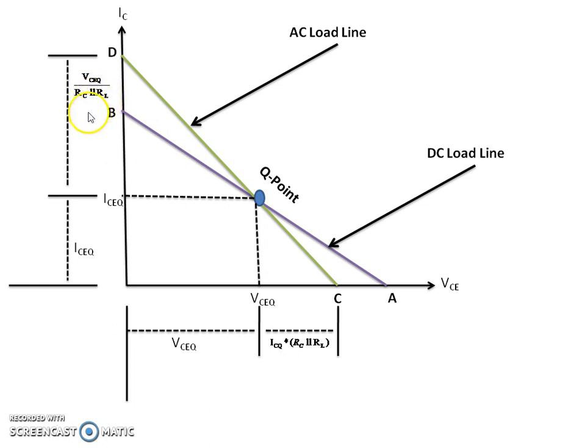In the same way, the DC component can also be evaluated. For the DC load line, this component A is exactly equal to VCC, but it can also be realized another way. We know that from the origin to the Q point intersection, this component is VCQ.